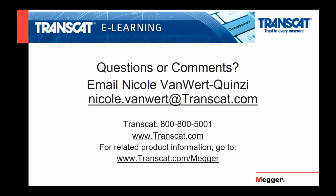Okay, what does Class A mean? Well, that's a good question. So Class A would be an instrument like the MPQ 1000. More and more customers around the world require a Class A certification for their PQ measurements. And this is important because different instruments aggregate their data differently. If you have two different units, you can get two different readings on each one.